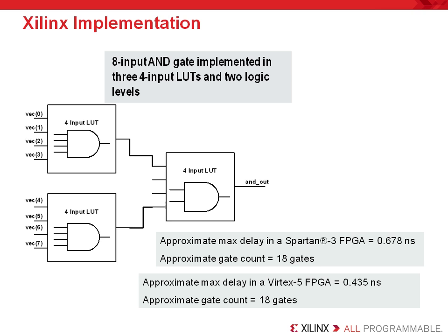Designs that are ported to FPGA technology from an ASIC always have paths that infer multiple levels of logic. Improving these paths is sometimes a big issue with designers trying to obtain peak performance in an FPGA. That is because the LUT cannot be widened and, by its nature, is input limited. And coincidentally, all FPGAs are limited in this way. Until the FPGA industry builds a high-fan-in combinatorial logic resource, this challenge will not go away.